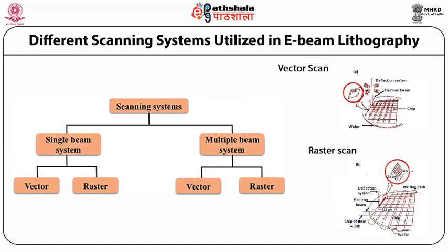The scanning systems for E-beam on the resist coated surfaces. The E-beam scanning system for moving over the resist layer could contain single or multiple beams scanned over the resist layers in vector or raster scanning modes. Various scanning systems are categorized in Figure 10.